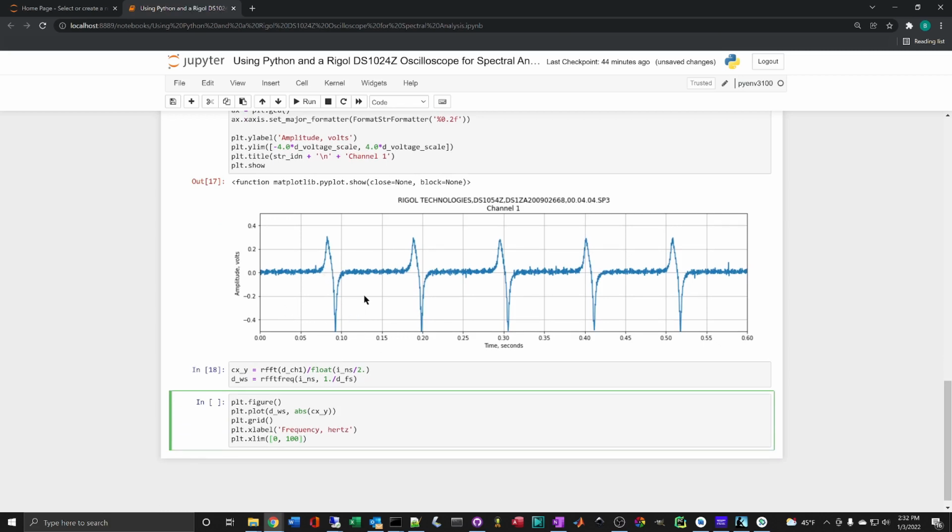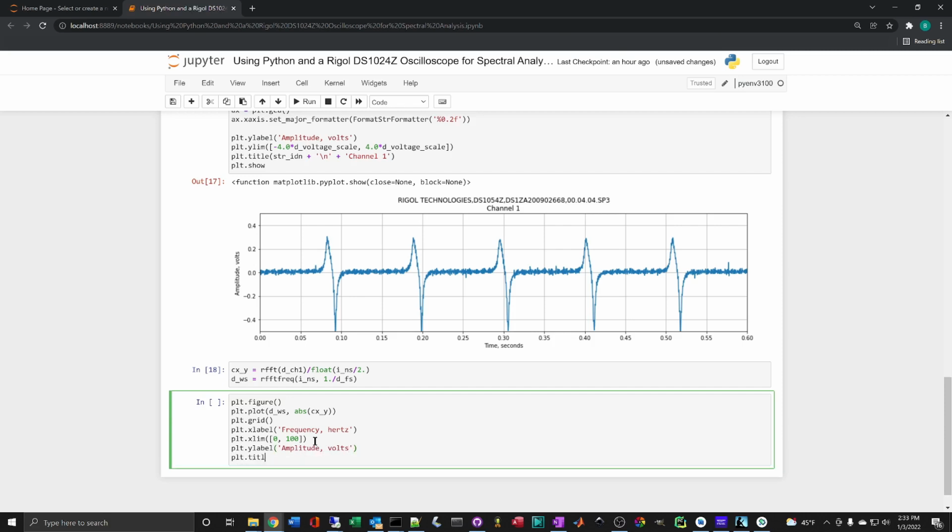So we're going to want to look at those fundamental harmonics and be sure when we look in that FFT that we have at least one fundamental frequency there at about 600 hertz, and we should see a harmonic because this is anything but a nice pretty sinusoid that we're looking at there. We're also going to want to label our y-axis. We know that's volts because this came right from the oscilloscope. And we're going to put a title on there too. And we'll show that.